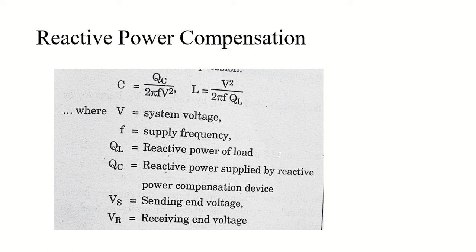Similarly for the reactors, for my inductance value, what will be the formula? It will be V square upon 2 pi f into QL. Here QL is again the reactive power of the load, and here QC is the reactive power supplied by the reactive power compensation device. Okay,